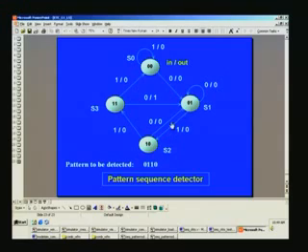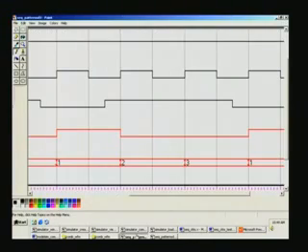So we had gone to and fro earlier. We are coming back, right? So that's what it is. So if it is 1, what happens? From 1 to 2 it has gone. In 2, now again the bit pattern 0, 1, 1, 0 has been encountered. That's why at the last 0 the output goes to 1 here. So this is the corresponding output. So whenever 0, 1, 1, 0 occurs, even in a recurring fashion, you should have 1 here corresponding to that.